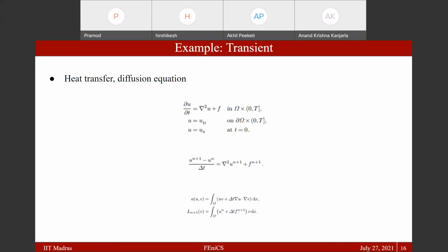You should be able to run it. When you run it, you will be able to generate a PVD file. In that PVD file, there will be multiple VTU files, right? Then you can load that and you can see the time series, as Rishikesh has shown in his crack propagation in mode 2 shear problem, right? So the entire animation, you might be able to see it.